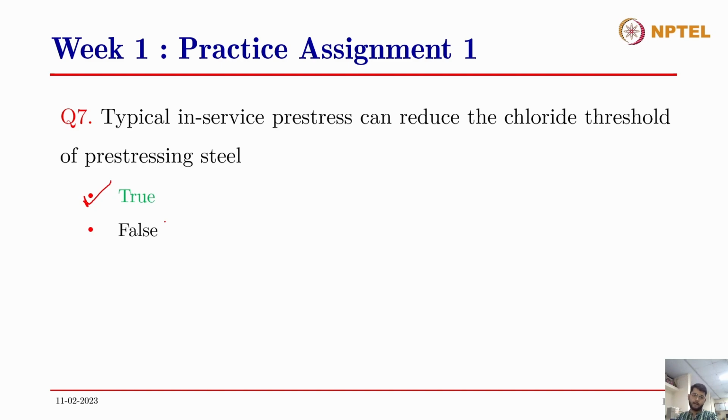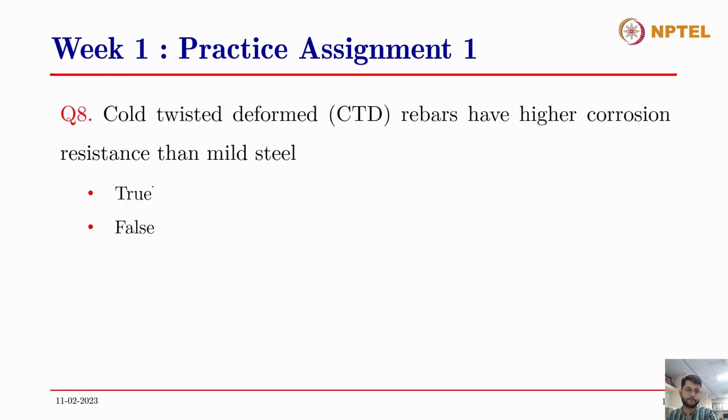So yes, typically in-service pre-stress can reduce the chloride threshold of the pre-stressing steel and hence make it prone to chloride-induced corrosion as well.